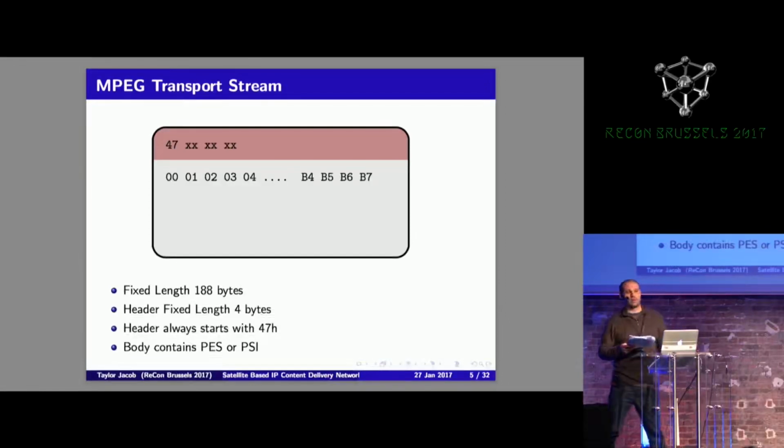In the case of this presentation, specifically IP traffic. So the main difference between DVB-T, C, and S is the transmission medium. For T, it's the air. For C, it's a copper cable. And for S, it's the Earth's atmosphere. The physical interface is generally referred to as a MUX in all three DVB flavors. In the case of DVB-S, it's also referred to rather erroneously as a transponder. And once the signals are demodulated into a bit stream, they're virtually identical.